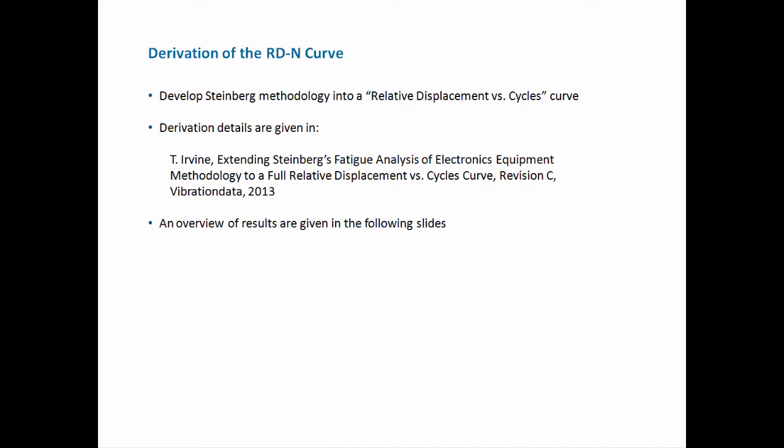And that way is given in the paper you see here: Extending Steinberg's Fatigue Analysis of Electronic Equipment Methodology to a Full Relative Displacement versus Cycles Curve, Rev-C, Vibration Data, 2013. This paper is posted on my blog. You can download it freely. And for those of you that like to get under the hood and tear apart the engine and see what's inside, I encourage you to review this paper.